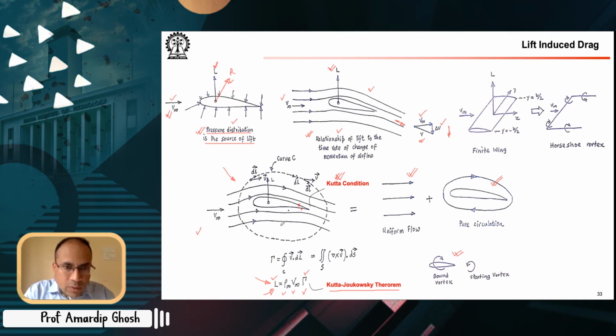And so now, if you remember what the circulation is, all you have to do is draw a hypothetical boundary, and there all you have to do is figure out, at every point, the local dl vector. dl is just a small element of that boundary. Take the local velocity vector, and work out this integral. Okay, so v dot dl across the entire contour, and that will give you the strength of the circulation, or also the strength of the vortex that is being generated somewhere.